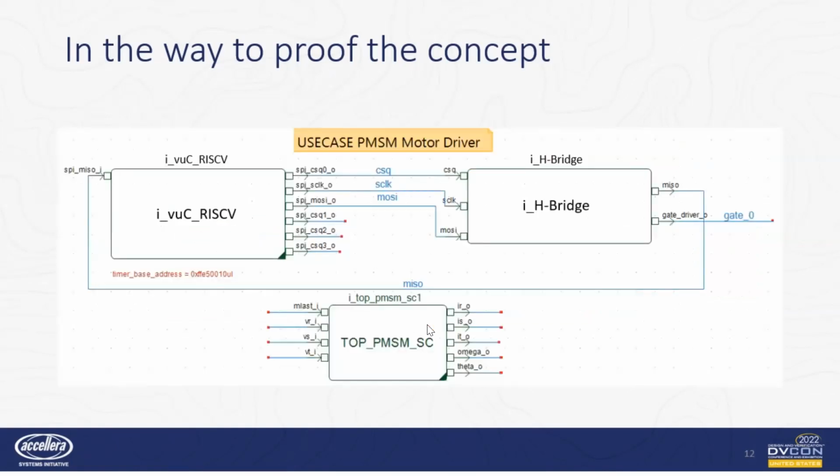One level above, this creates the base of the virtual prototype that will support the test bench for the time metrics to be acquired. Using TLM, the firmware has access to the values of the motor model: current, voltages, position, and speed. This platform serves as the basis for the proposed test bench.